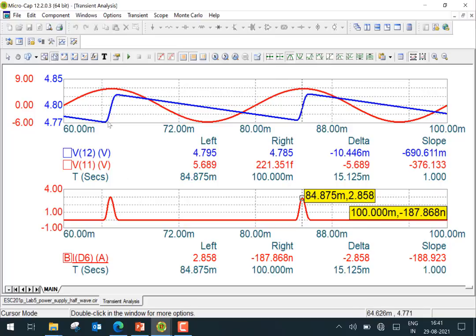Because the diode is conducting for a very short period of time. And in that short period of time, it has to supply the entire load current of 100 milliamperes. So 100 milliamperes is flowing for almost the entire period, but the diode has to supply it because the source is through the diode, right? So it's 3 amperes here. And we saw, if you remember, the diode characteristics around 3 amperes, we had 0.9 volt drop across the diode, right? So you can see the thing here.